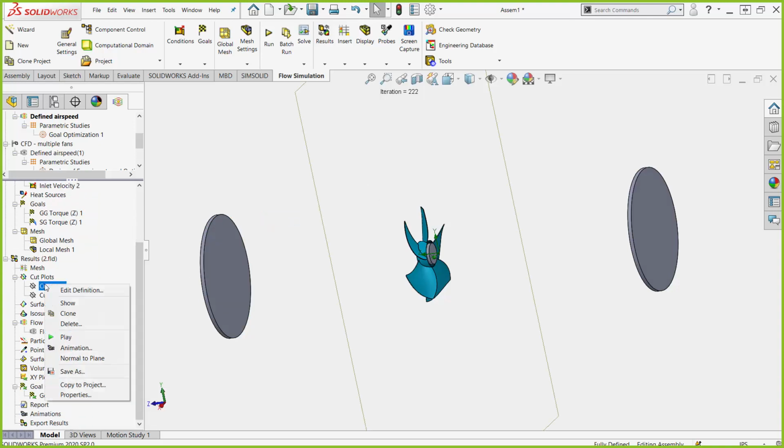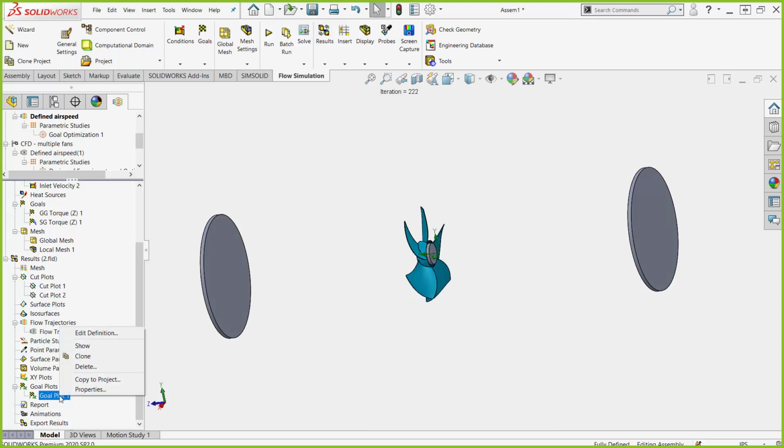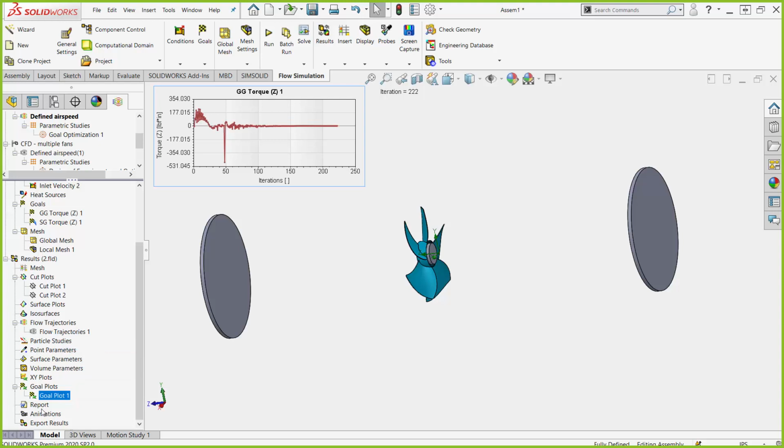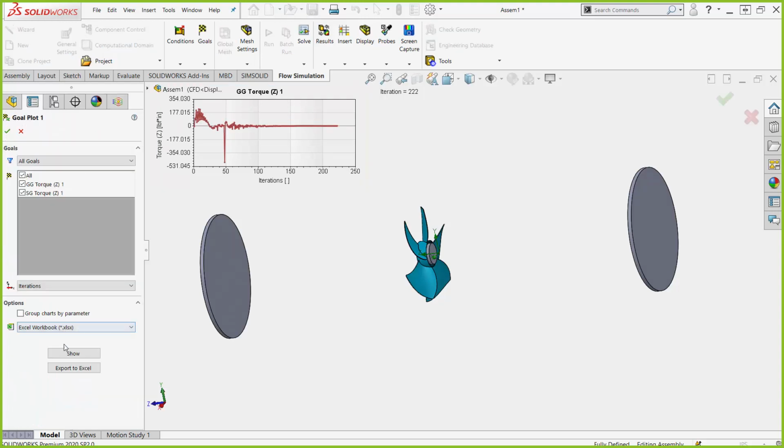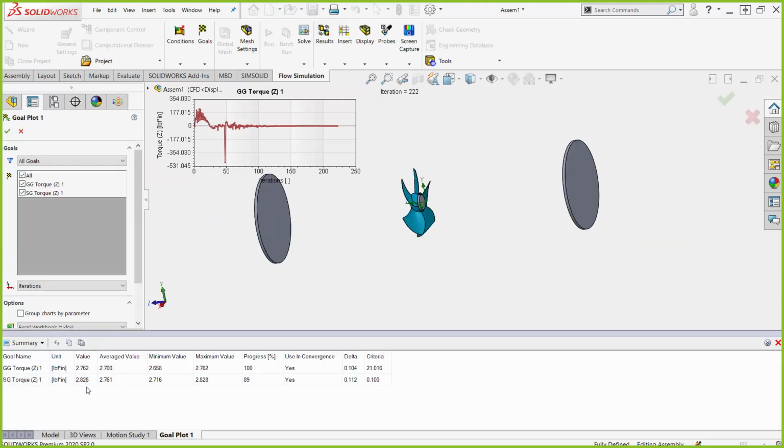I go through and I get various results again. Now, when I go and look at my torque values, let's look at that over here. I can see that my overall final result ends up at about 2.8 inch-pounds. So the fan, 20 RPM is incorrect. The fan would still be forced to either slow down or speed up. I don't know what is true yet.